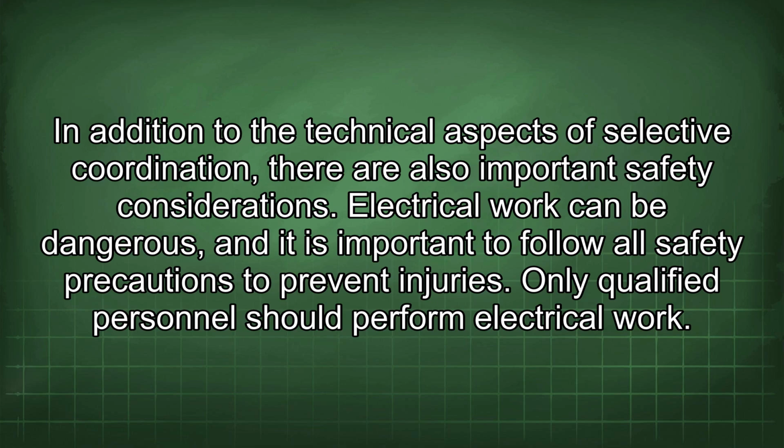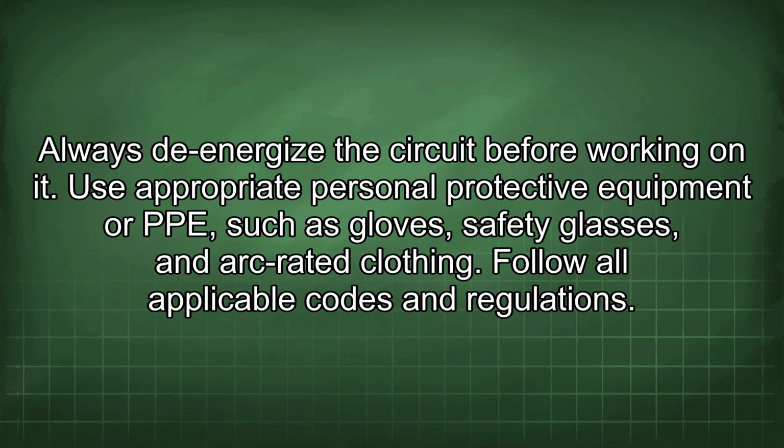In addition to the technical aspects of selective coordination, there are also important safety considerations. Electrical work can be dangerous, and it is important to follow all safety precautions to prevent injuries. Only qualified personnel should perform electrical work. Always de-energize the circuit before working on it. Use appropriate personal protective equipment or PPE, such as gloves, safety glasses, and arc-rated clothing.